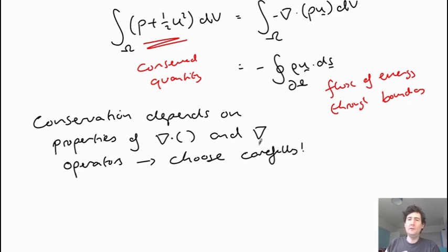Typically, if you have nonlinear, say limiter schemes, then they don't obey these relationships, and so that can break the conservation of energy. And so for these kind of terms, you can use things like central differencing methods. And so for some codes I've been involved in, it can be useful to split the terms into different cases. So some of them where we're evolving the quantity directly, so say conservation of mass, you can treat as fluxes through cells.